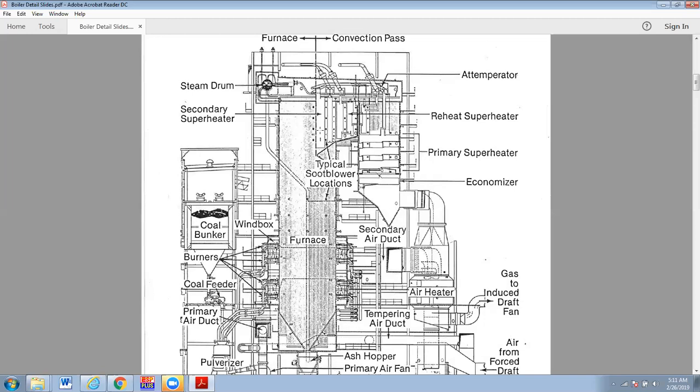Okay, so our hottest flue gases pass across the secondary superheater. There are soot blowers involved. We're showing reheat superheaters. There could be more than one. This could be a secondary, and we could have a primary back down here. It just depends on how much heat transfer area and the design of the boiler. But we're going laterally through the convection pass. The convection pass is lined with tubes, not only to suck up heat, but to cool the convection pass itself, the structure of it.